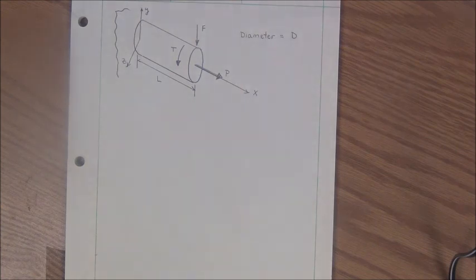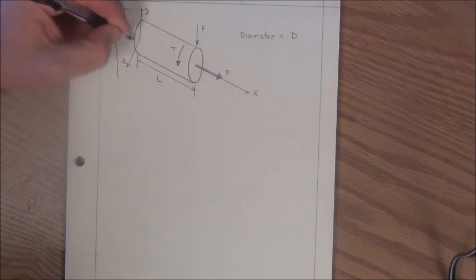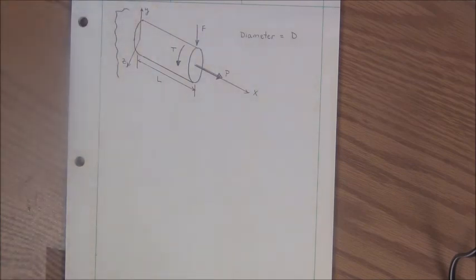I typically will look at stress elements at the top of the cantilever beam and also at the side of the cantilever beam, because based on this loading, that's where the maximum stresses will occur.